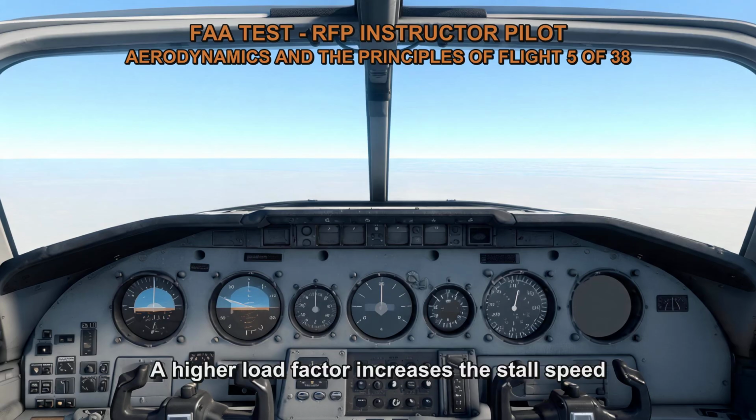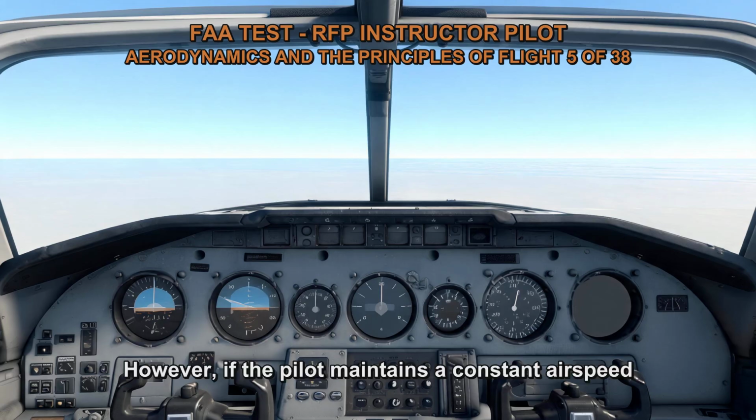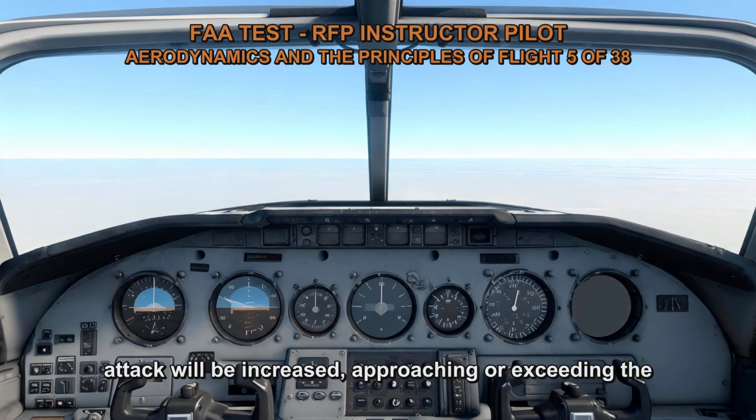A higher load factor increases the stall speed of the aircraft, which means a higher airspeed is required to maintain level flight. However, if the pilot maintains a constant airspeed during a bank turn, the aircraft's angle of attack will be increased, approaching or exceeding the critical angle of attack, which can result in an increased sink rate and a potential stall.